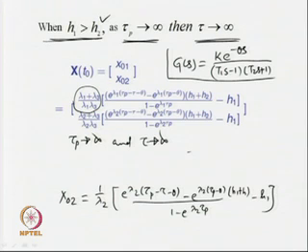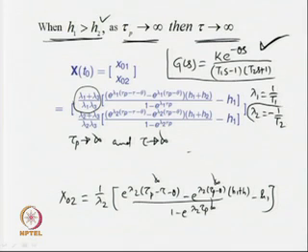You see where we have tau p minus tau also will be a large value. So, this is a large value. Again, this tau p minus theta will be a large value. Here tau p is a large value. Now, what about lambda 2? As you see, given this is the dynamic model of the open loop unstable system, lambda 1 is equal to 1 upon T 1 and lambda 2 is equal to minus 1 upon T 2. So, lambda 2 is a negative number.